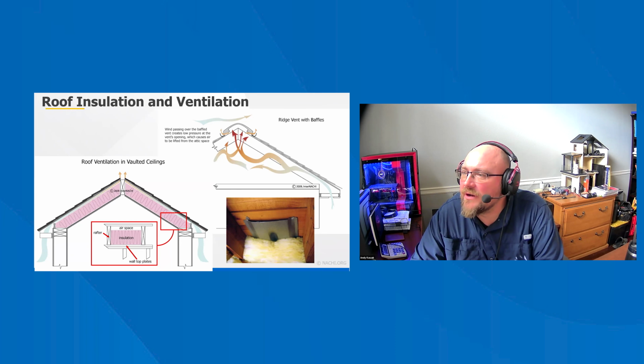For vented wood-framed pitched roof systems, the primary concern is the potential for moisture to build up at the sloped underside of the roof deck during cold weather. The underside of the roof deck is the condensing plane. Where vents are installed at the eaves, the insulation should not block the vents or free flow of air. Where eave or cornice vents are installed, insulation must not block the free flow of air.